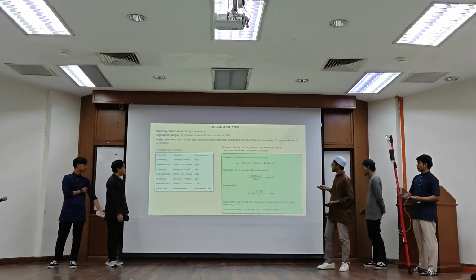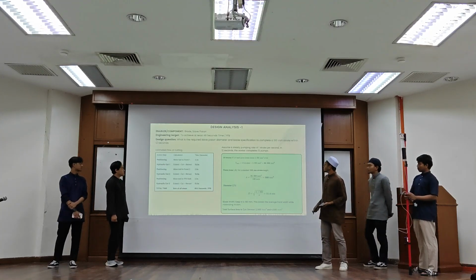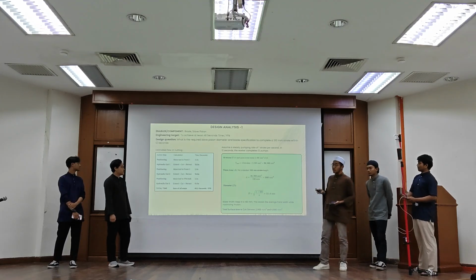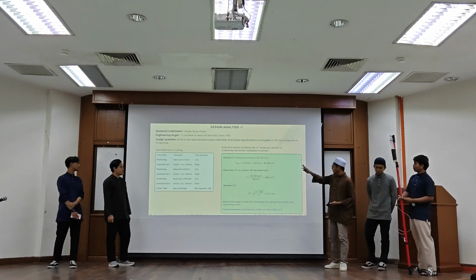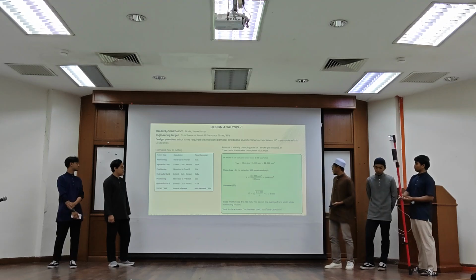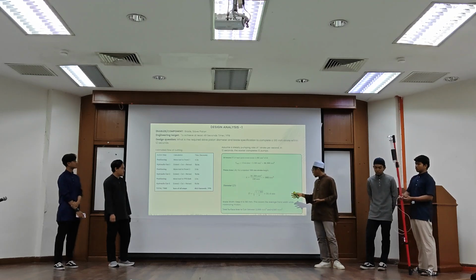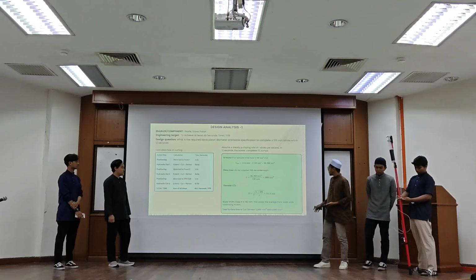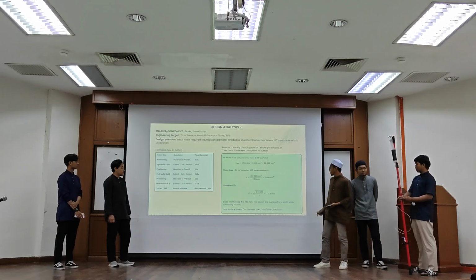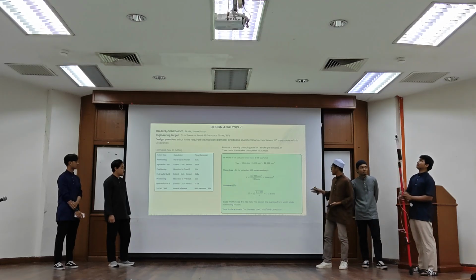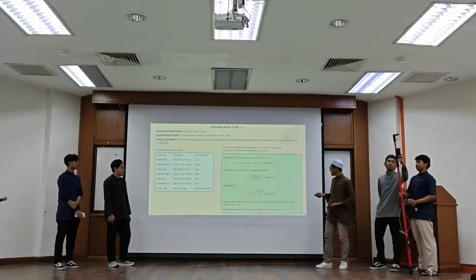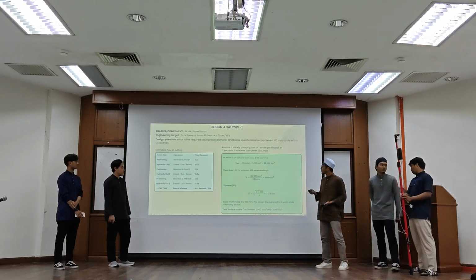For design analysis number one, we need to find the slave piston diameter, angle, and also the blade spec. After the calculation, we found the surface area to be cut is between 2000 mm² and 4500 mm². So the blade width is 160 mm, and the diameter of the slave piston is 24.1 mm.